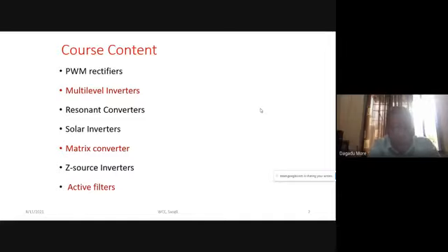In power electronics, you have studied DC to DC converters, another name for which is choppers. You know that we have to operate the choppers at high frequency, with switching frequencies of a few megahertz, so that the values of L and C required will be less.